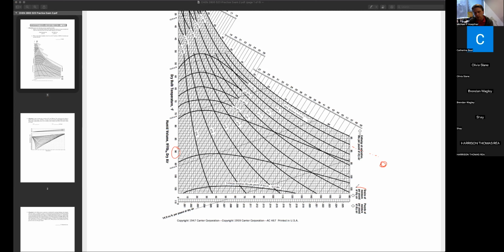And so we have the grains of moisture per pound of dry air. So it's not grams of moisture. Oh yeah, that's totally grains, what I meant. And so if we were to get to this point and draw down on that chart, it would be 200. I think I have one on the Canvas page that has that information a little bit better. So that's one source there.